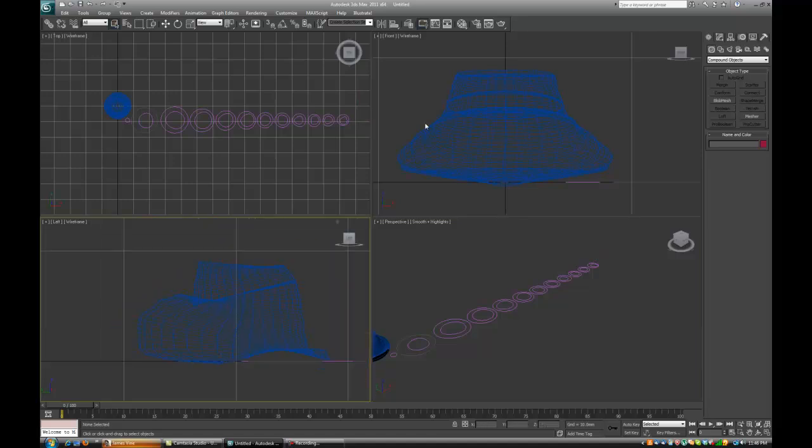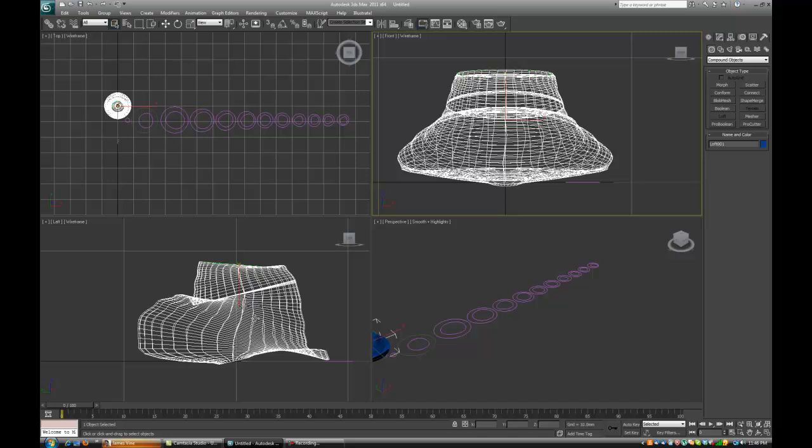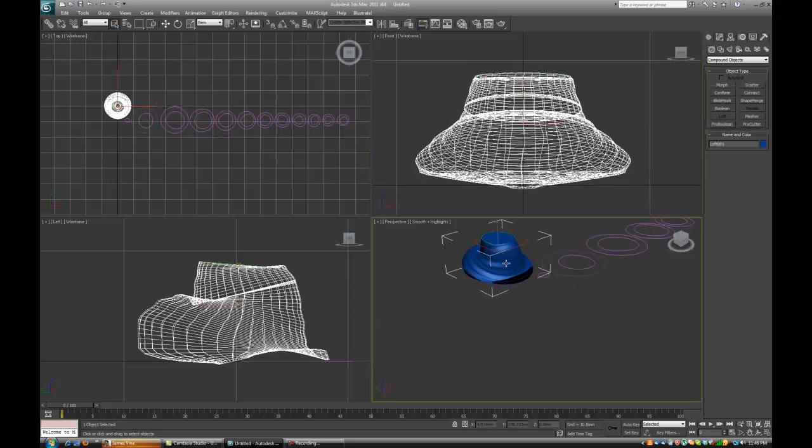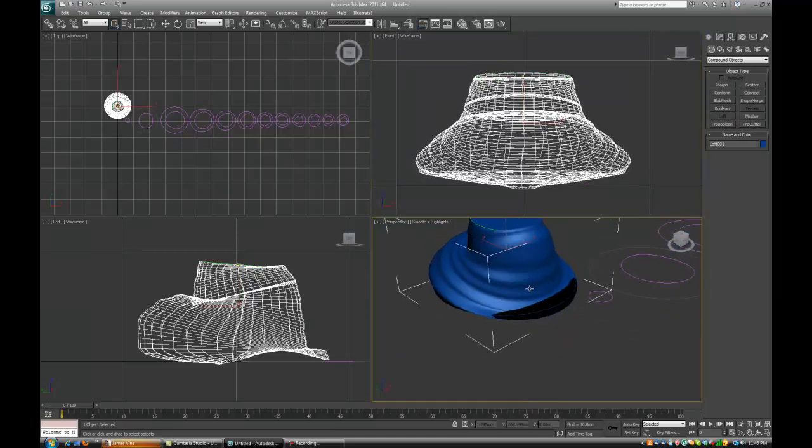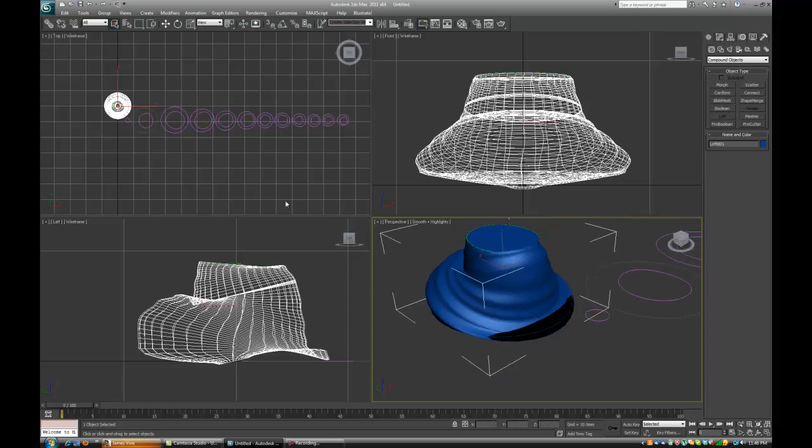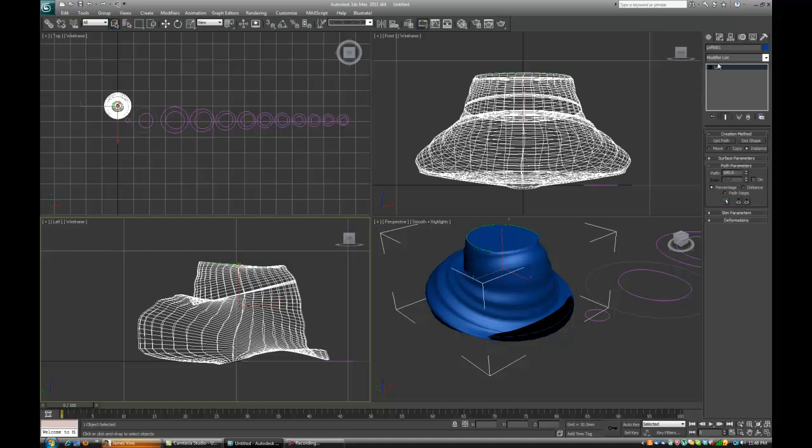Done. Now, as you can see, we've got an incredibly ugly blob which doesn't really convey what we're talking about, and that's probably because I haven't actually made this with a straight line. So what I'm going to do is show you guys how to edit the line after you've actually finished lofting the curve. To do that, if you select your loft and you come up to this panel here, it also looks blue on a lot of other 3ds Max versions. If you select that, it'll give you the loft options, like as we had before when we were creating it.